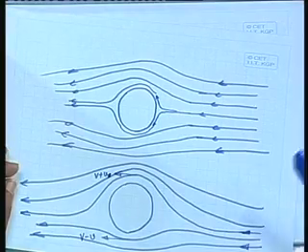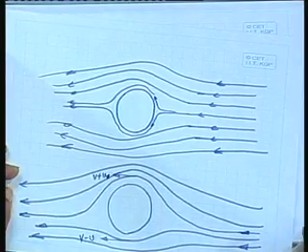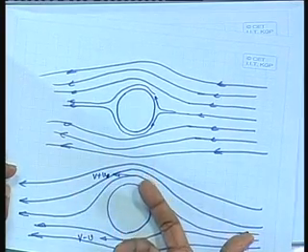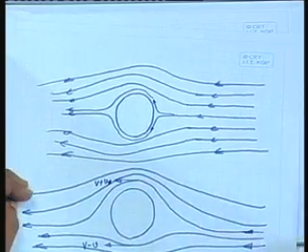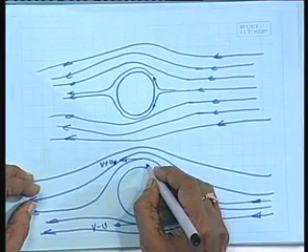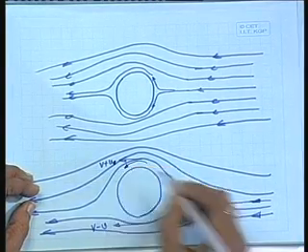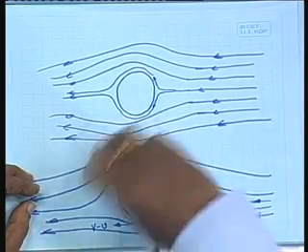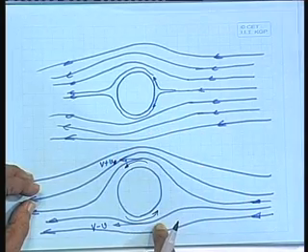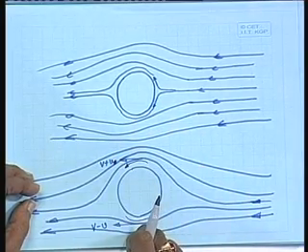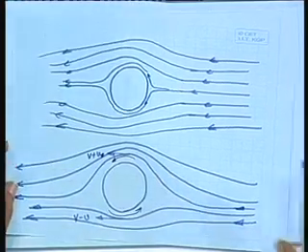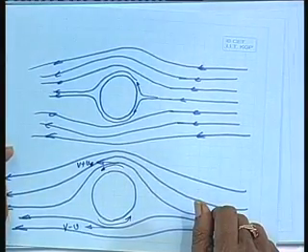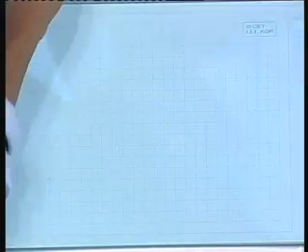If the vortex was this way, it would be the reverse. It depends on which way. You see here, I have imposed a vortex flow like this. So, there is an addition here and a subtraction here. This is what I have shown. Okay? So how do we generate circulation? We will see that. On an aerofoil, it is very easy to see how the circulation is generated.